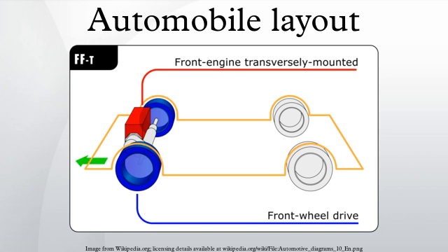Steering radius. As no complicated drive shaft joints are required at the front wheels, it is possible to turn them further than would be possible using front-wheel drive, resulting in a smaller steering radius for a given wheelbase. Better handling at the hands of an expert. The more even weight distribution and weight transfer improve the handling of the car. The front and rear tires are placed under more even loads, which allows for more grip while cornering.